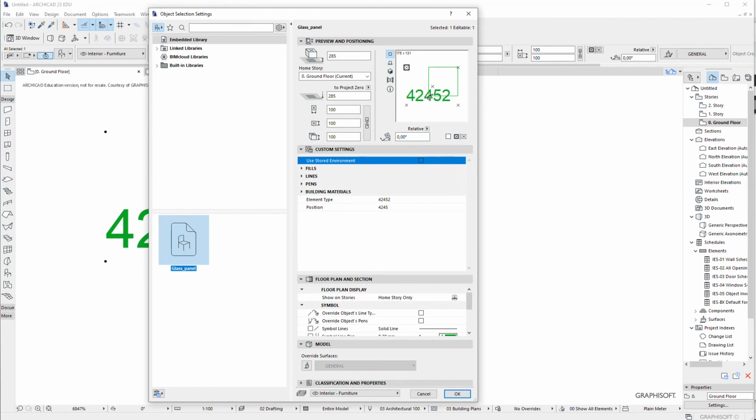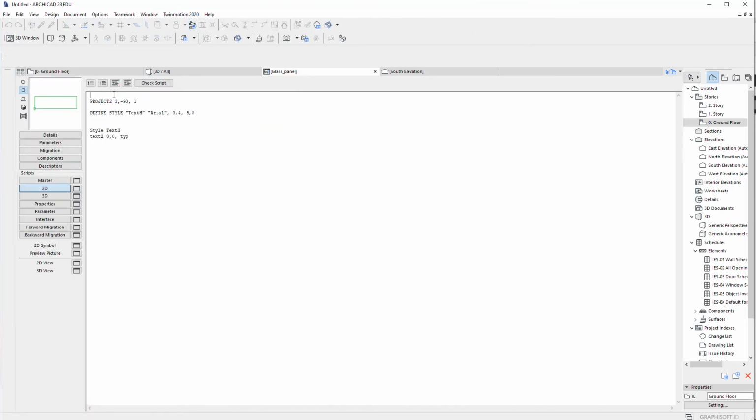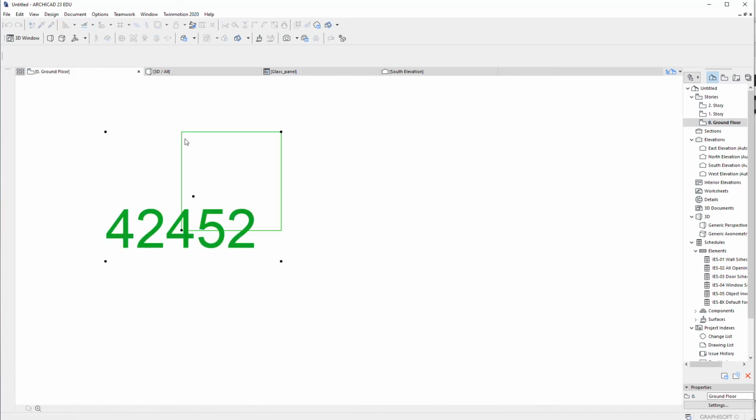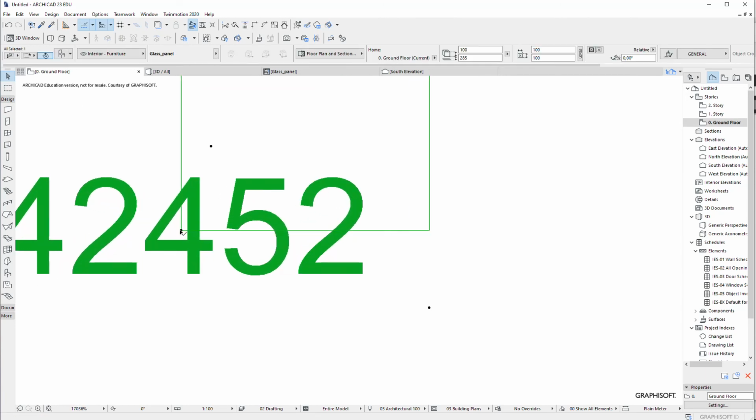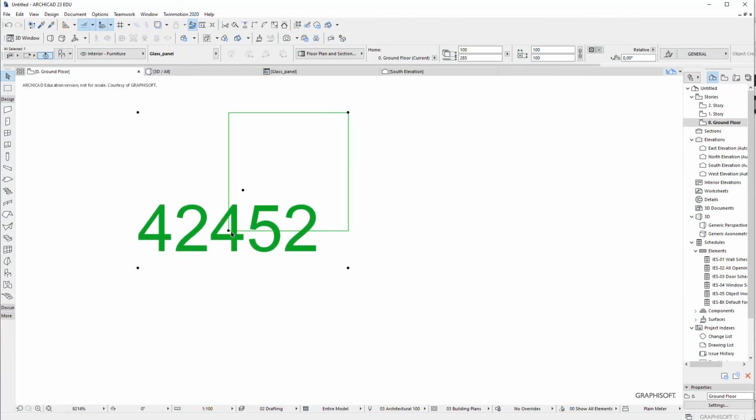See it like here, it's like drawing from this object. This is the 0, 0 where I have it. I can make a hotspot to make it clear for me where this 0, 0 is. Let's make hotspot 2. I make it by 0, 0 like an anchor point. Control S. Now I see this hotspot showing me where the 0, 0 of this object is. It's like right here.